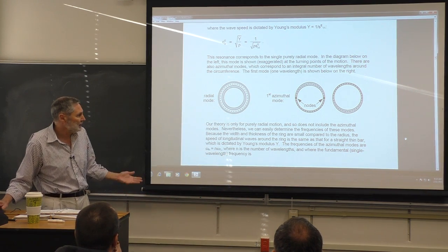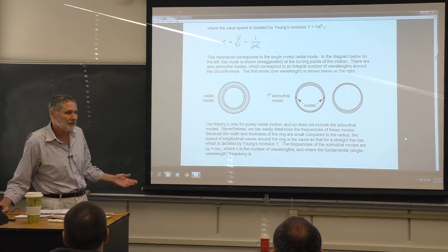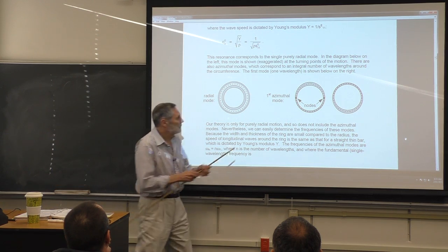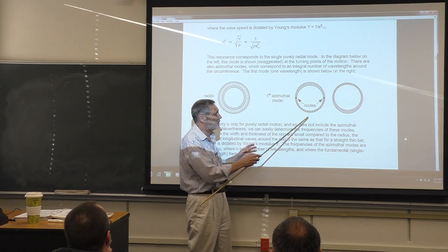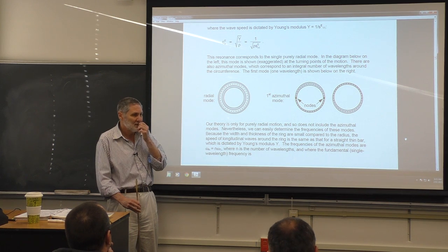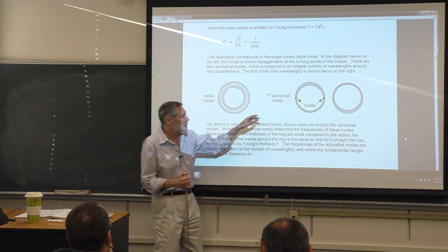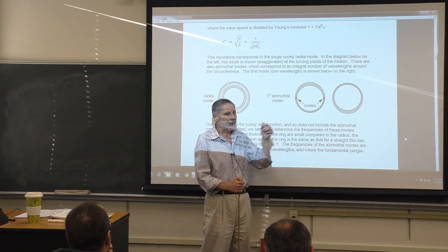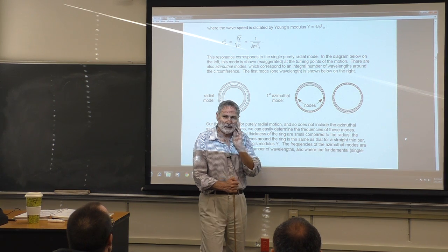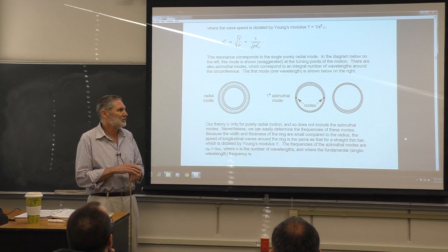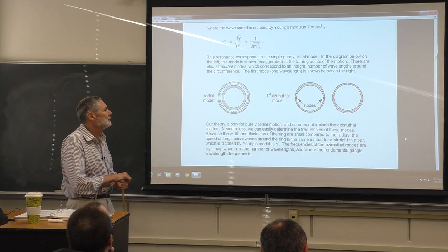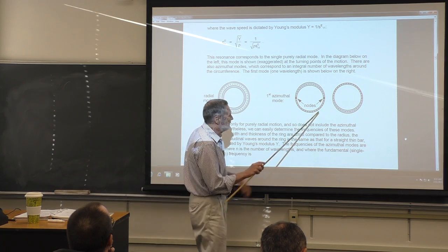So we can easily write down what the resonant frequency is going to be. And the wavelength here is large compared to the transverse dimensions. As long as the wavelength is large compared to the transverse dimensions, the Young's modulus will be the appropriate modulus, as we've discussed before, right? Now, if you go to very high modes, we have a really tiny wavelength here. It won't be the Young's modulus anymore. It'll be the modulus of unilateral extension and compression. I wish they could come up with some kind of short name for this. Okay, but that's much higher.